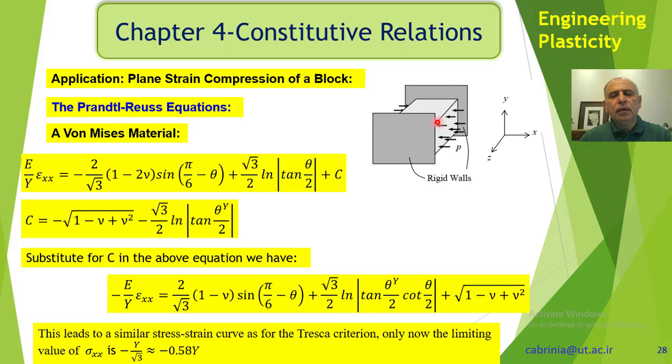The trend is the same, and I should mention that as we press this block, at first we have an elastic region. Okay, so if we release the pressure, it will go back to its original shape, because when you press this block, it cannot move in the z direction. It can only move in the y direction and x direction.